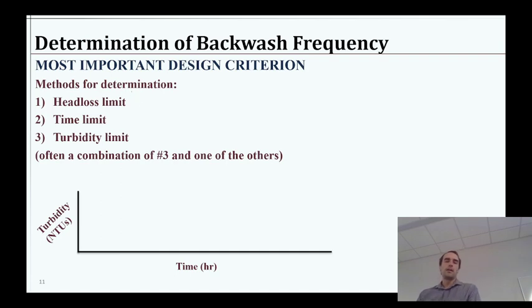So either we can go with a head loss limit. So at some point we have too much pressure, and we are either concerned about causing fissures to form in the sand media like I mentioned, and say, okay, well, we simply cannot go above this threshold because then we're going to have potential to have escape of particles. Maybe we use a time limit. And we say, okay, well, just based on operators' experience, it never goes well if we go past 72 hours. Okay, maybe it's something like that.